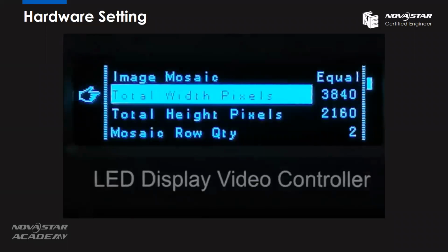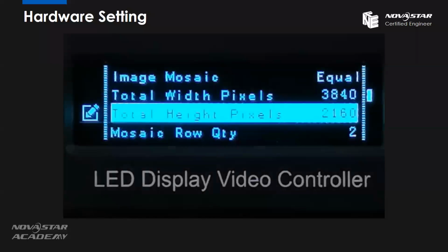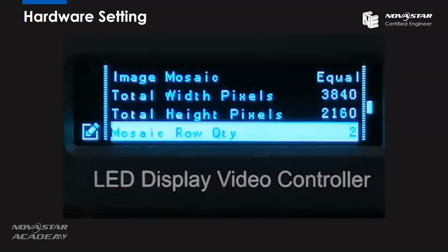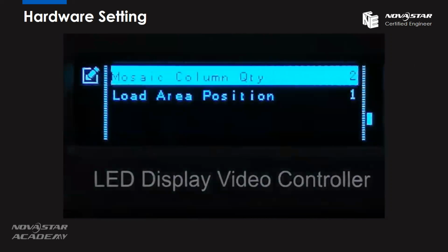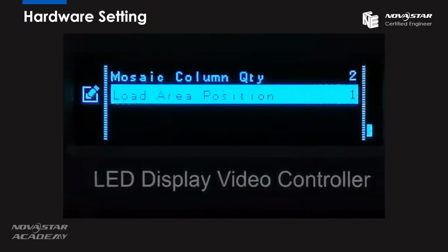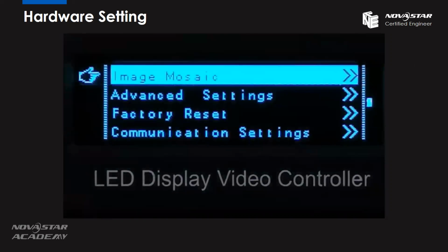So input the total width and the total height. And for our example, the mosaic row quantity is 2. It's a 2x2 area. And the mosaic column quantity is also 2. So there will be 4 load area positions, 1, 2, 3, and 4. And we should do it 4 times for every VX4S to let the sending card know, okay, you have 4 brothers, and you should splice this 4K screen together.